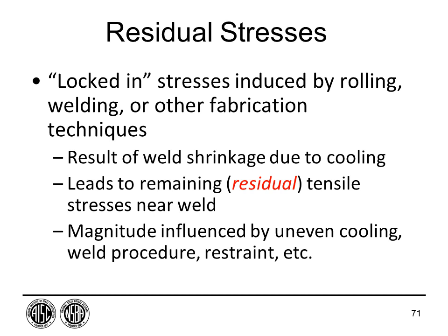The weld is a liquid metal, it's very, very hot, so it's expanded, if you will, and as it cools and begins to harden, it shrinks and begins to pull material with it. This, of course, then is an uneven cooling. So the first pass of weld is cooled, the next pass on top of it is hot. As it cools, it's restrained by the previous weld and so forth. And so our outer passes are generally in tension, and they can be as high as the yield strength of the steel.